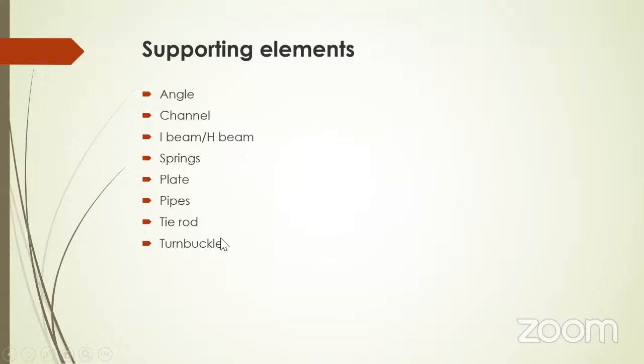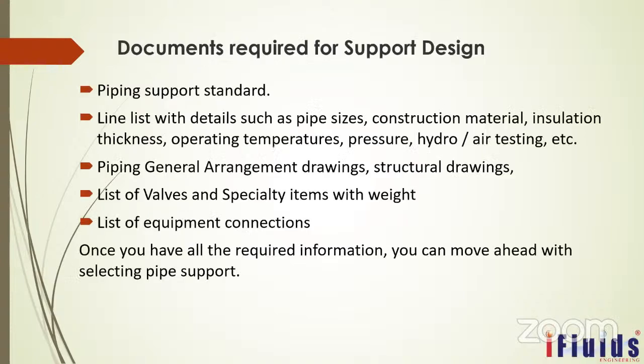They use the turnbuckle because during movement it may get loosened, and again we have to tighten it. So periodically you can check the tightness of the object. In the same way, in any shutdown or preventive maintenance of the support, or any high load test you are going to do, at that time you can check the turnbuckle arrangement, tightness, and looseness in the pipe support.